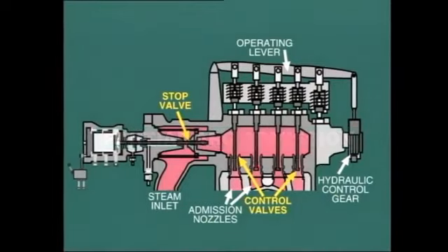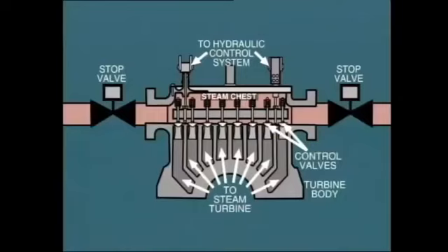Of course, when the turbine is on load, more of the valves are opened, thus providing more even heating of the nozzle block. On large turbines, this problem is particularly pronounced, and startup is usually performed in a different manner, that is, by full arc admission. In this case, the stop valve is closed after heating the steam chest.